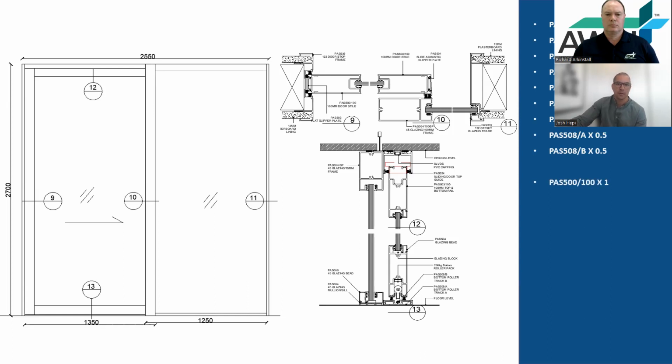And then the door component. So one door style, again, in this case, it's going to be half a length of flat slipper, because on the back of the slider, we have a side acoustic slipper, which I'll come to in a sec. We're going to do half a length, in this case, of top and bottom door rail, half a length of bead to match.